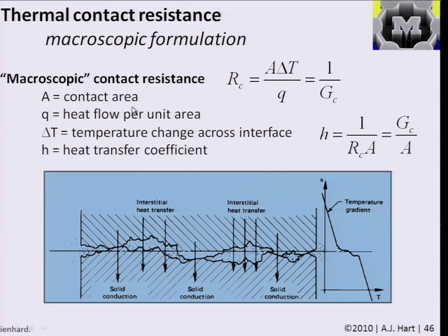And the same thing essentially happens when you have two nanostructures in contact, two carbon nanotubes. The heat is transferred very well along the nanotubes, but the heat is transferred by a significantly poorer margin at the interface. And the mechanical conditions of the contact between the two nanotubes determine what this local temperature drop, if you can really define the concept of temperature there, is at the interface.